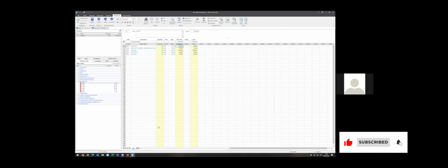Quite often you can get some of the quantities out of the model. And you could see in the demonstration that I showed some of the 2D stuff as well, that you can revert to your 2D drawings and do some manual measures. If you know that there are components that are missing that you need to make manual allowances for, you can certainly measure from the 2D as well as the 3D.